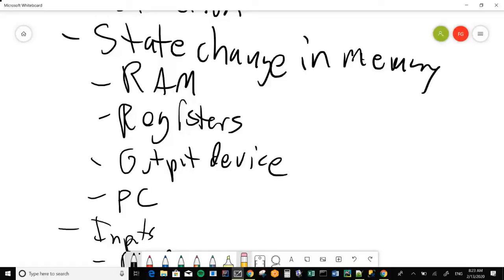Furthermore, we wind up having a lot of value in having this D register around. It's a nice place to temporarily park some data in the midst of performing a computation. Part of the reason we need it is if we didn't have the D register, we would certainly need two A registers so that we could be simultaneously specifying two distinct memory locations upon which a calculation is premised.